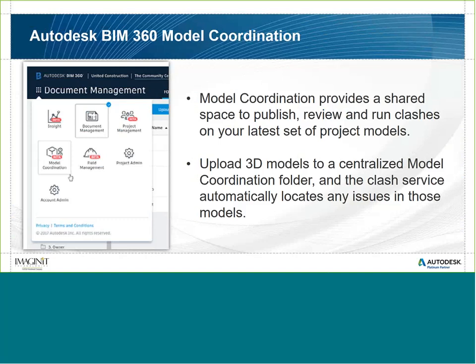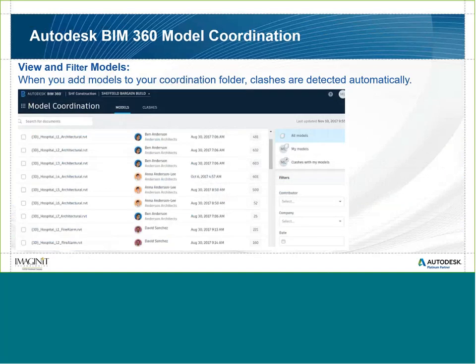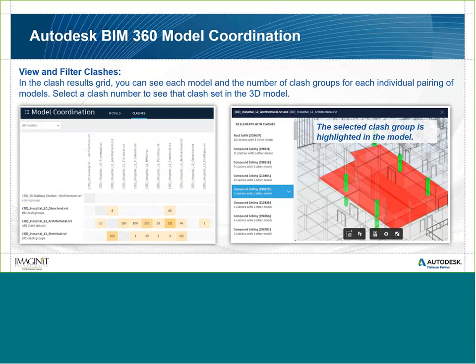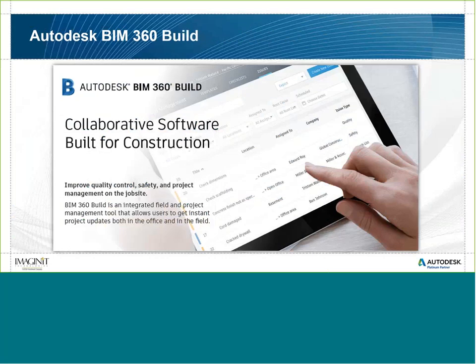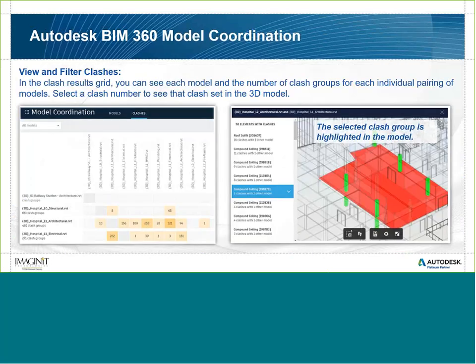If you buy access to the module, you access it from the same place. You keep your models in Docs. Again, everything is in that one place, that single source of truth. And you're able to take those models, filter the ones you want to see, and then see all the clashes. And there are different ways that you can group the clashes. You can filter them by the MEP objects first and how many things interact with a duct, or a structural element first and how many things interact with a structural element. So all of those allow you to do these things all within that one environment.